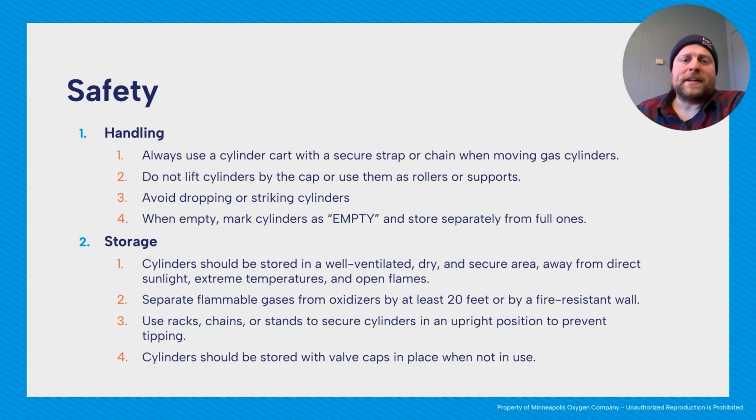All right, so handling: always going to use a cylinder cart. Always have the cylinder strapped to your cart if you're moving it around. We're not going to lift them by the cap. We're not going to roll them on the ground, on their side. We are going to avoid dropping or striking them. We're going to keep empty ones away from full ones.